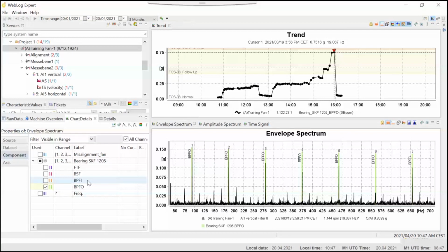So that also teaches us that if we install such a system on board of the vessel, we can say there's something wrong with the bearing. And then if you are a specialist, a mechanic, you probably understand what's wrong. You can decide to order a new bearing, and exactly the right one. And if you're not, you would call for help from your shore support to identify what is exactly wrong in this equipment. Or is it even less specific, that you don't know that there's a failure in the bearing, but maybe just a failure in the pump?